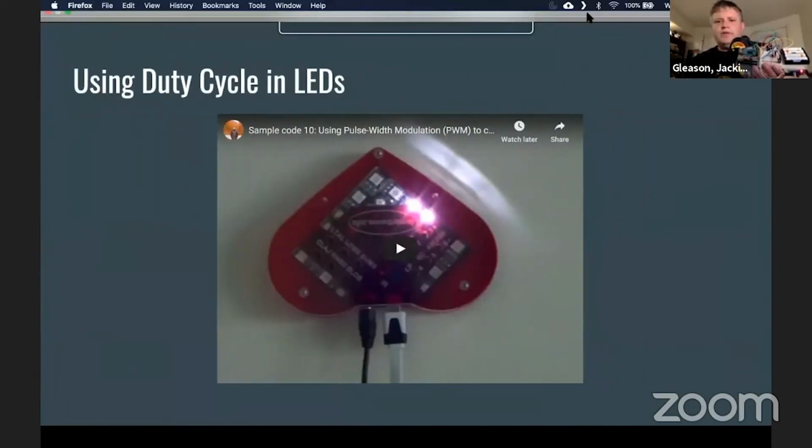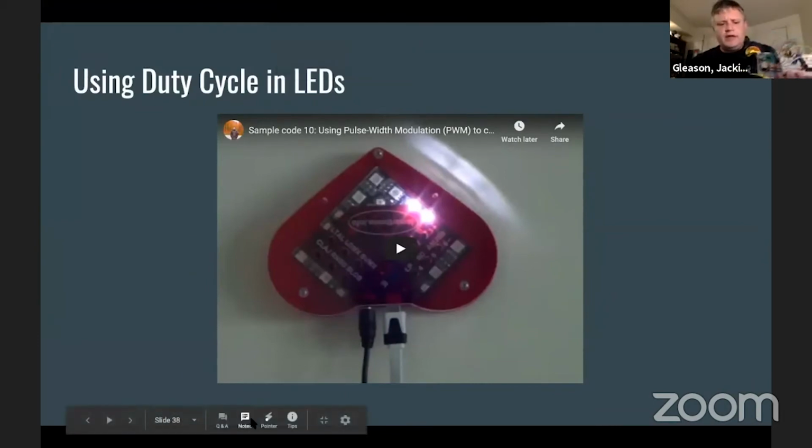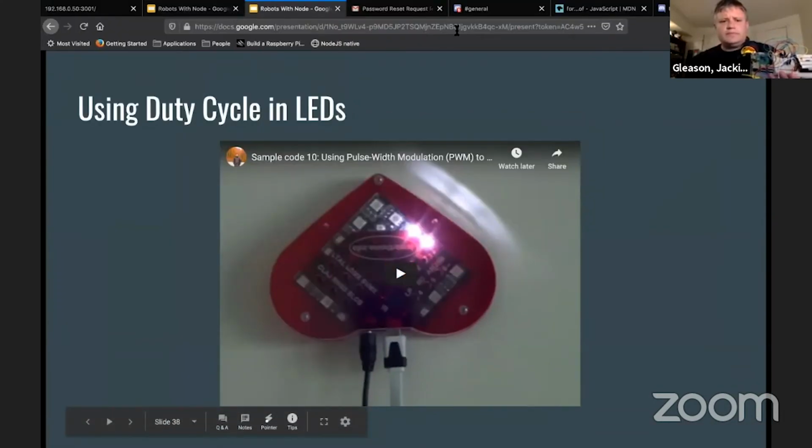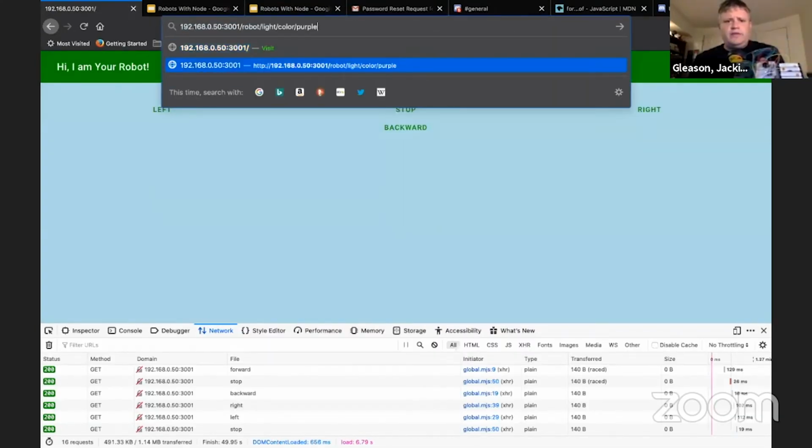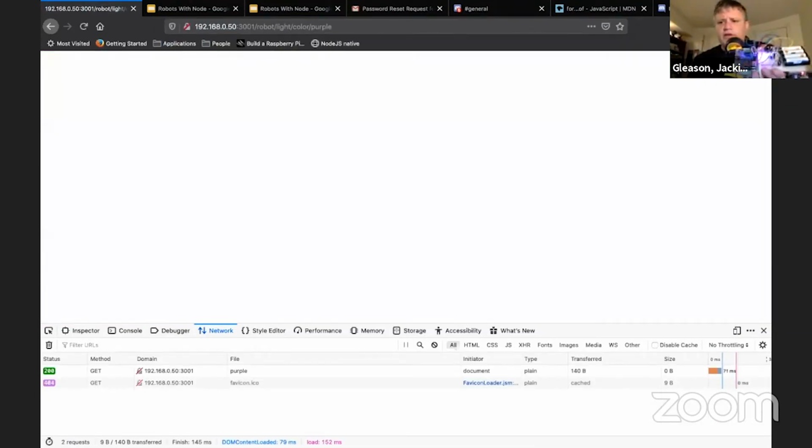So when we look at this, we can go ahead and, if I get out of here again, go back to here, and we can say something like this, and it'll go ahead and turn the, I don't know if you can see that in the video or not, but you can see where it turned the color purple, right? And the reason that can happen is because it's an RGB LED. With pulse width modulation, all of the different LEDs can operate at different light levels. And so you can use that duty cycle to go into your RGB value, and then you can use that to dim or lower the individual values, right?